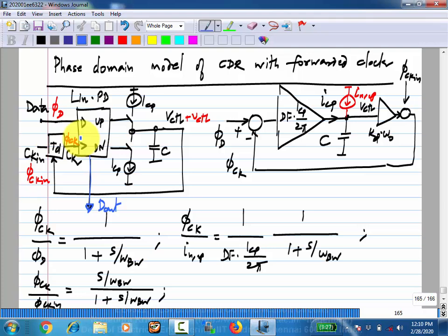Okay, so then you apply a jitter at a different frequency. Then again you go on increasing the amplitude of the jitter until the bit error rate crosses 10 to the minus 12. So then you again find the amount of jitter that can be tolerated and so on. Okay? Is this fine?